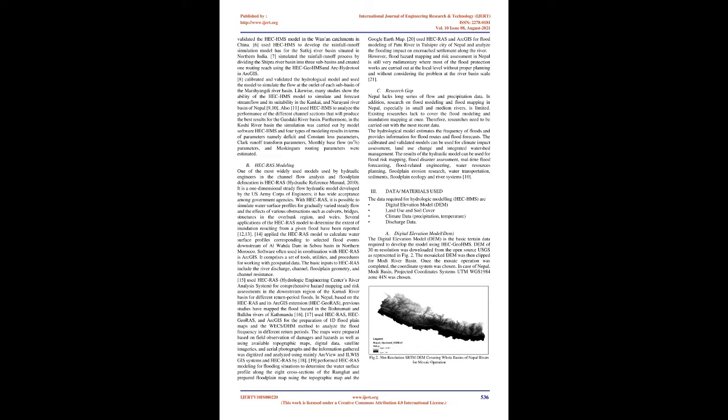It requires daily rainfall, long-term average monthly potential evapotranspiration, discharge and stage data of the basin, for calibration and validation, and geographical information of the basin to get the simulated runoff as output too.